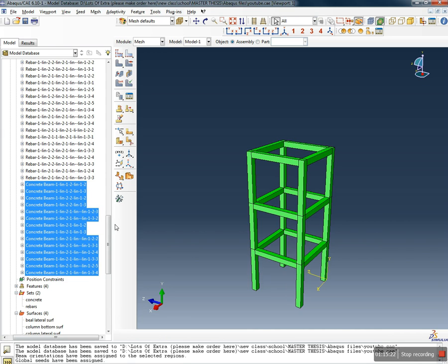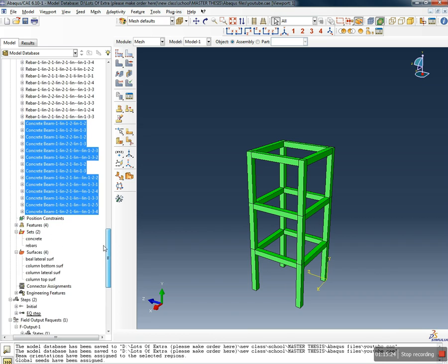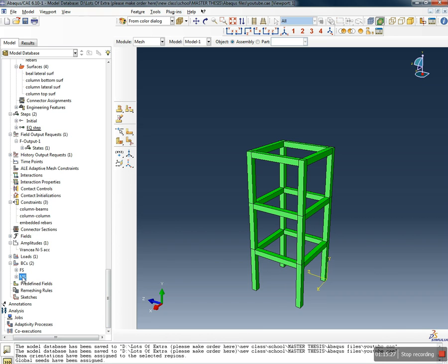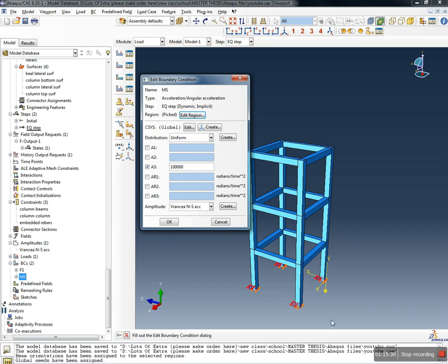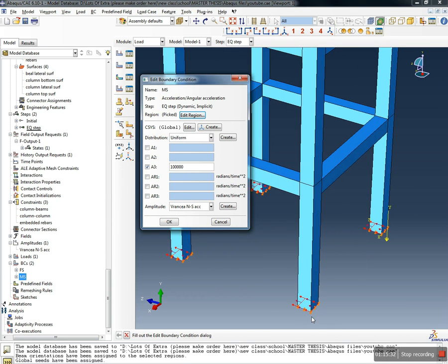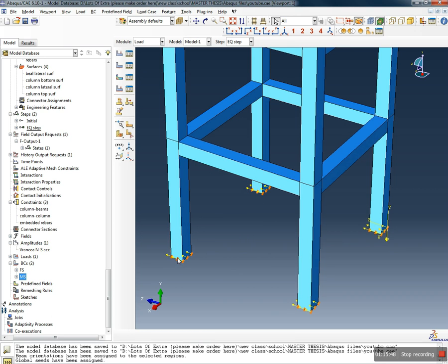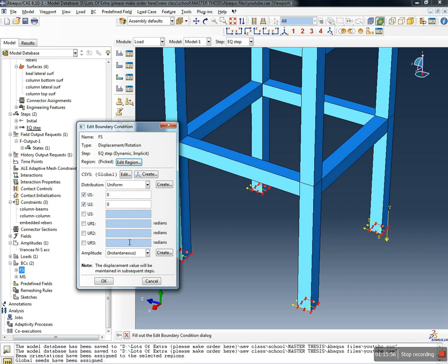resume. Yes, and now let's see if we still have the boundary conditions. Yes, we do, because otherwise we would have got some warning that the region does not exist anymore. I was a bit worried that since we suppress and resume again, it might not work. But it works. So if you define boundary conditions and then suppress the regions where you define boundary conditions, and then resume them again, your boundary conditions will be fine, which I'm sure is not valid for mesh.